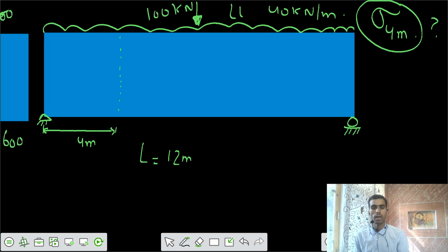And the cable profile is that your cable is a straight line profile. That's a bent cable, and it has eccentricity 100 and 200. If there is a neutral axis somewhere, this is your neutral axis, and the cable has some eccentricity at the ends and at the midspan.